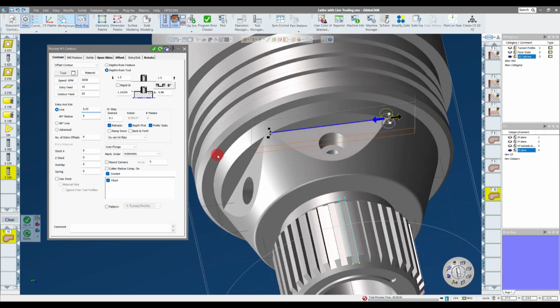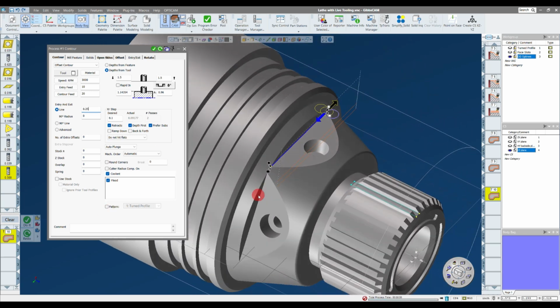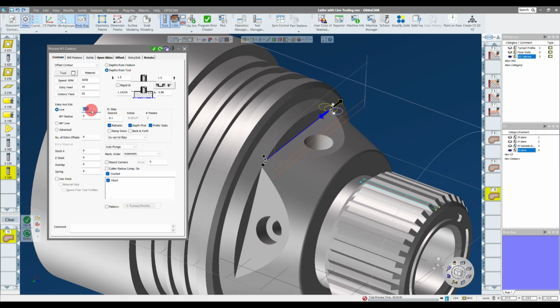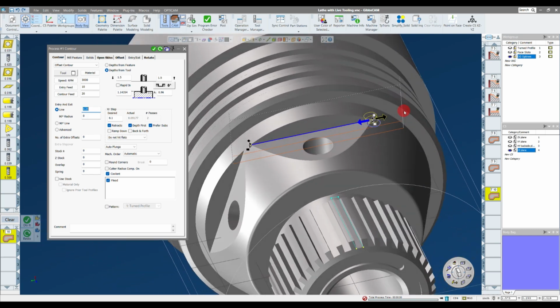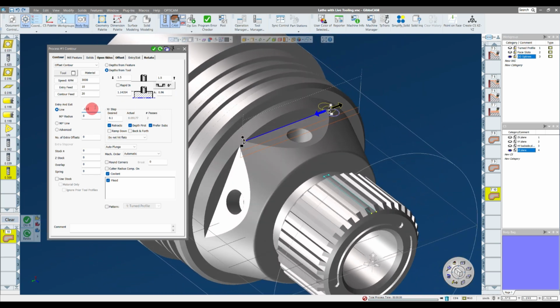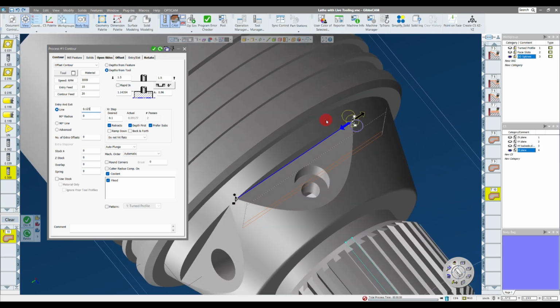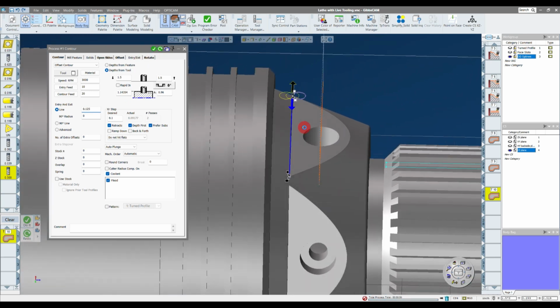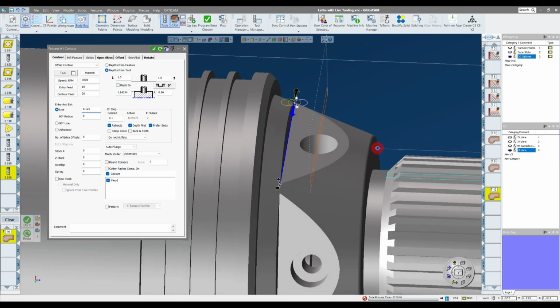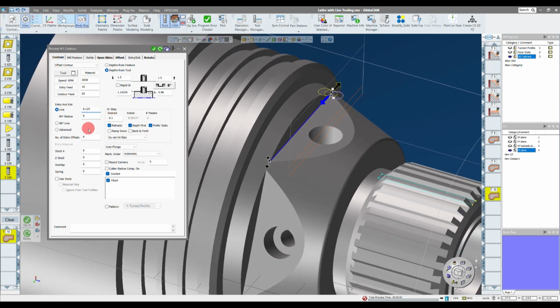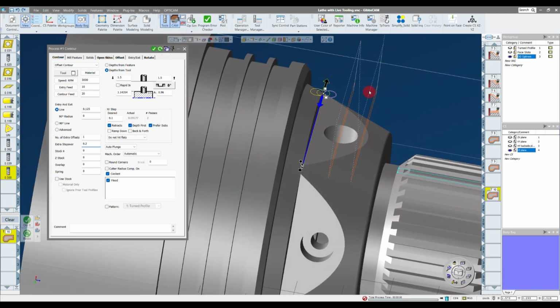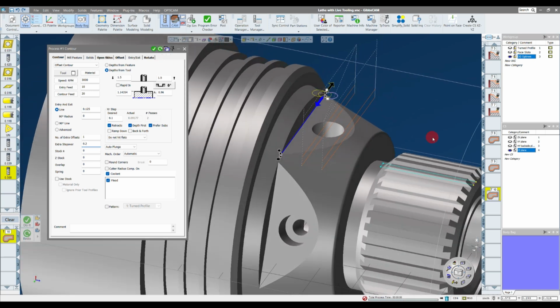Now you just want to make sure that because we're using the y-axis on this, you're not extending further than the travel that you have allowed on your particular machine. Maybe I'll take that a little bit less just to mitigate that risk. And if you're concerned that your tool isn't wide enough to cover this face, you could also give an extra offset here. So I can give one offset and maybe give a 0.2 step over. And then if I click redo, it'll do it in 2 steps just to make sure it covers that entire face there.